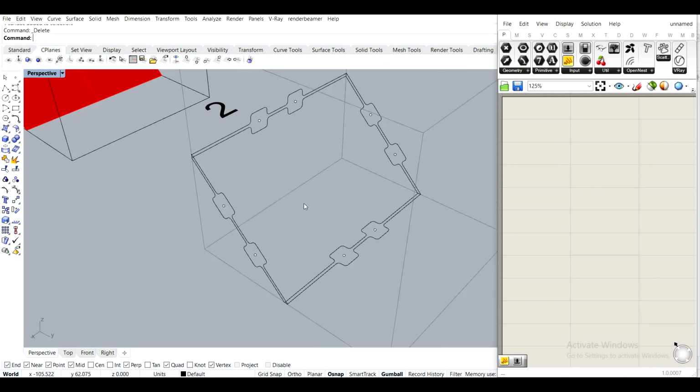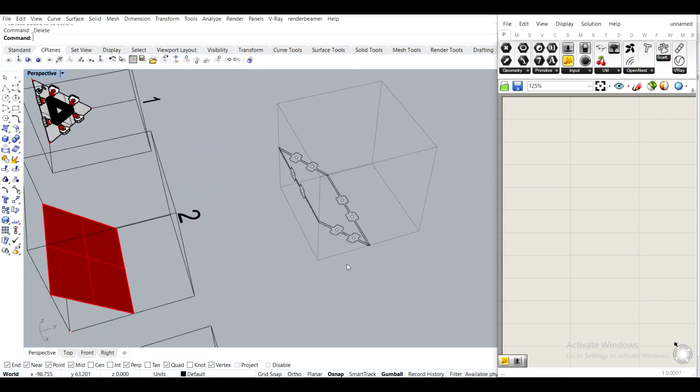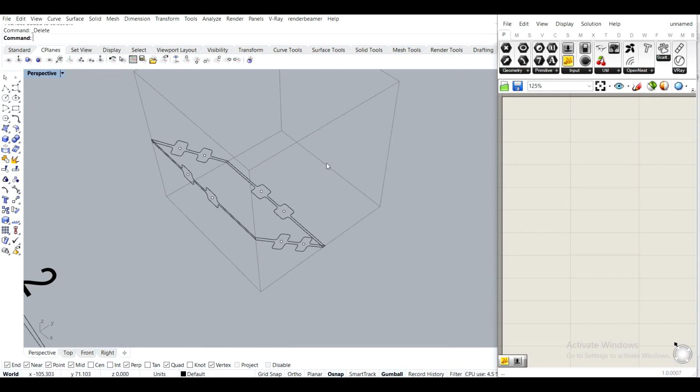So that's my guide. Okay, so now instead of modeling it out, I will use what's called structural optimization. And it's a voxel-based procedure where basically a Grasshopper script carves out all of the unnecessary geometry according to certain stress loads or stress flows throughout the voxel space, and it leaves only the geometry that's needed for the object to hold that particular load in that particular point.